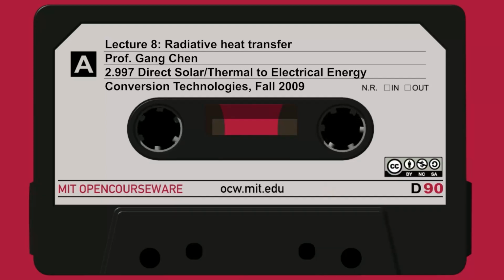And if you do the total, we have the summation. Summation is basically the energy balance. The energy leaving surface I and reaching J and K combined is the same as the energy leaving I reaching J plus leaving I reaching K. So with those relations, for simple geometry, you can find the view factors from a table, or you calculate using this relation rather than doing those complicated integral algorithms.